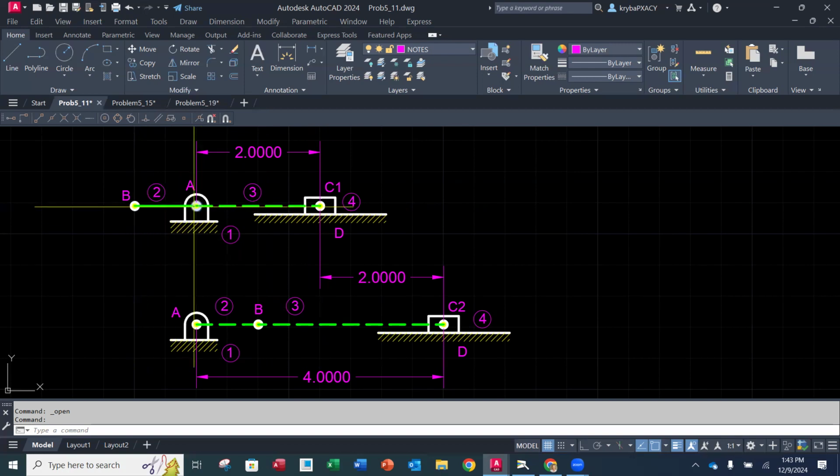So notice that my center of rotation for my crank is in line with my slider. Okay, so it has to be because of our Q equal to 1. That means that it's the same stroke time out as it is in. So now this is going to rotate around, and now down here in the other extreme position where C2 is all the way out,